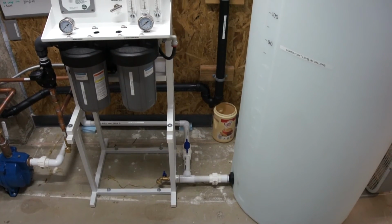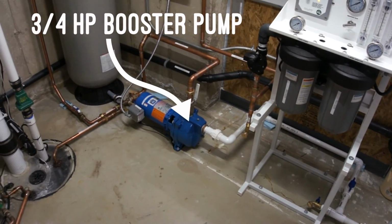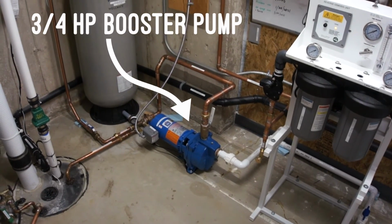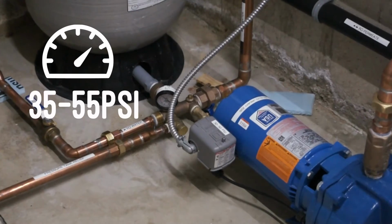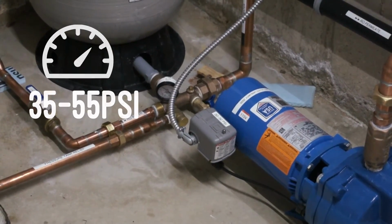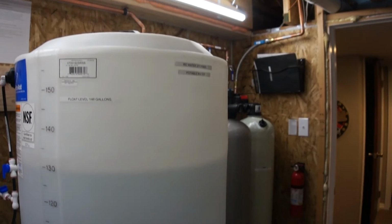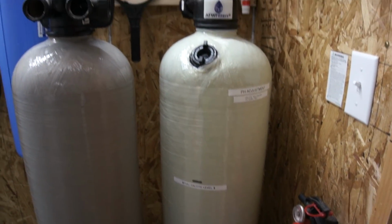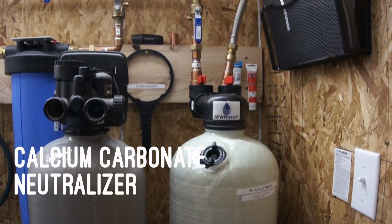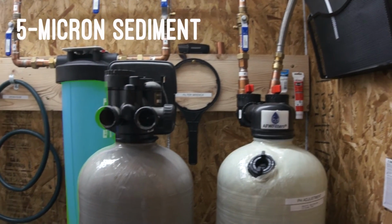Now that we have clean water, we have to get it back into the house plumbing. A booster pump draws water from the tank and pumps it into a 30-gallon pressure tank. This pressure tank operates between 35 and 55 psi. The clean water is then fed through a series of pipes to a neutralizer. Water tends to become slightly acidic during the RO process, and this neutralizer uses calcium carbonate to neutralize that. The water then passes through a final filter to remove excess neutralizer.